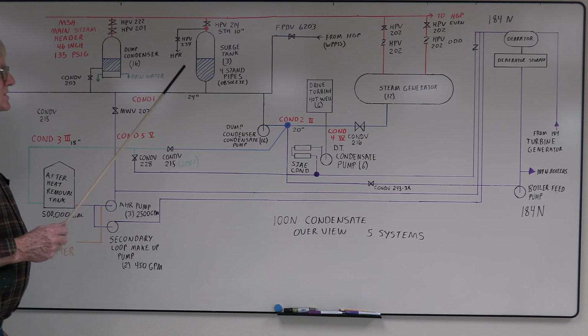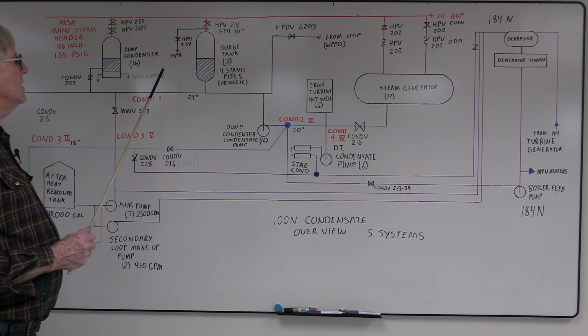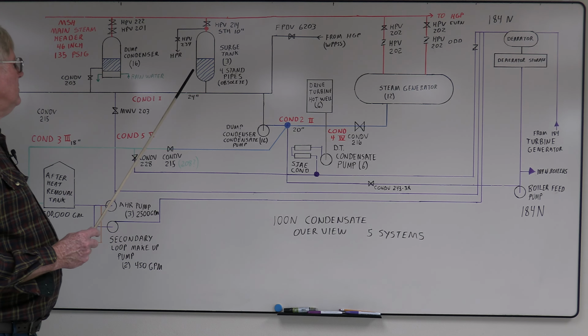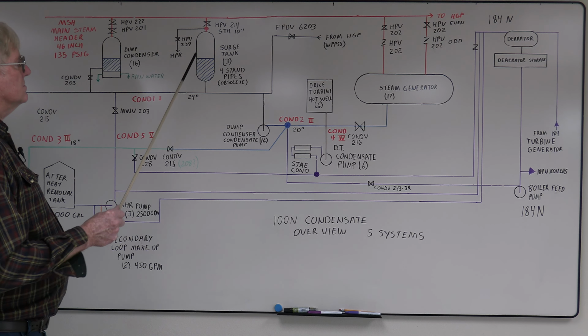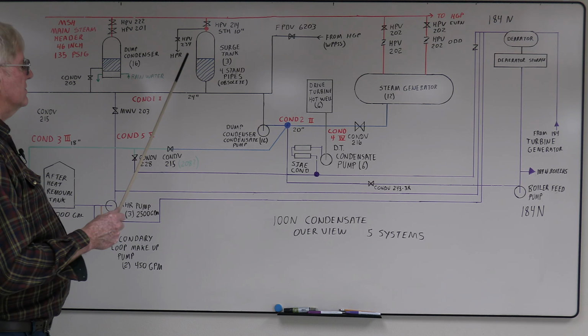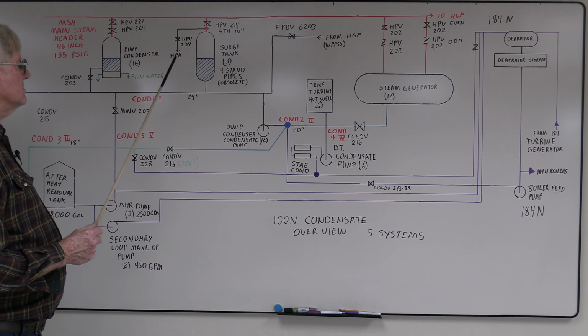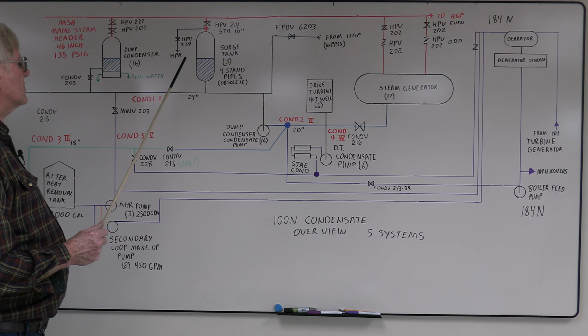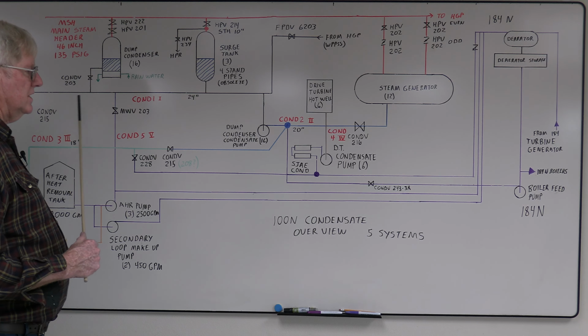It's just your center surge tank, had the controls on it. The outer 2, they were just there for volume control. So this whole setup here was just to take care of surge for startups, shutdowns, scrams, and it's kind of inventory control that you can maintain the system with.